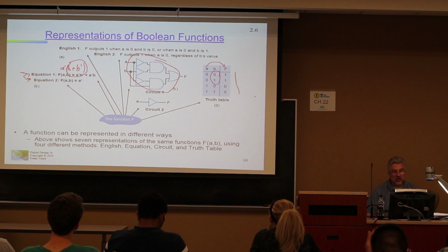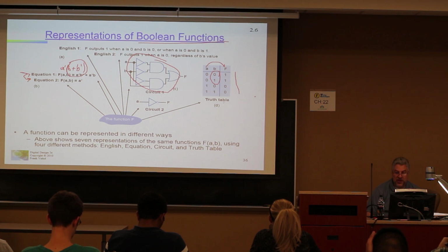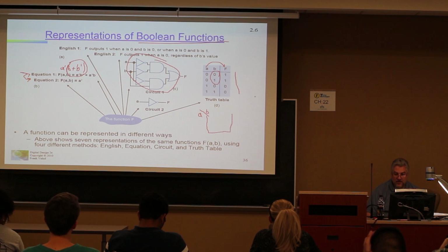So what's the way you really know how to do that? Well, it really comes down to Boolean algebra is one of the best ways to identify how to simplify. But the other option I'm going to give you is K-maps, which we'll look at later. And in fact, if we were to look at this for a K-map, you would say, based on B up here and A down here, it is a 4-entry. So when B is 0 or B is 1, A is 0, A is 1.